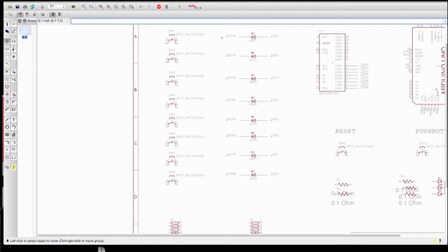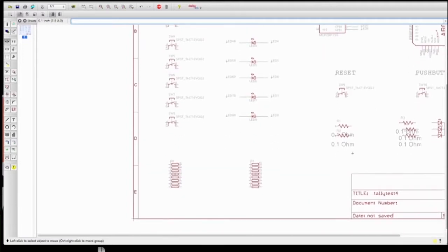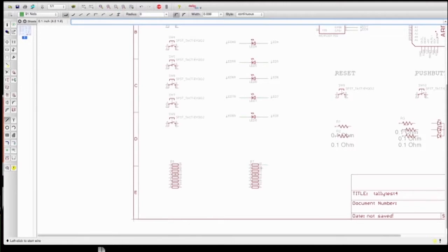All right, so there's our LEDs. These are all connected now to over here. But what we haven't finished yet is the resistor side. Now, in the fast forward, you may have seen me label these LED 1 through 8, and then an R at the end for resistor. So I need to come down here, and I'll do this through fast forward too, but I'm going to go to this resistor right here and add in all the same thing I did here. One side goes to ground, and one side goes to the LEDs. So I'll do that in fast forward mode again.